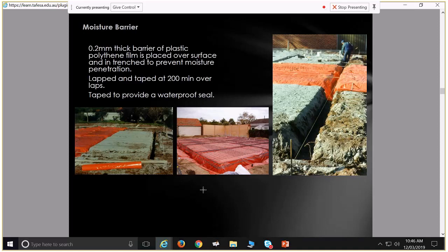But how about the termite sheet? Will it be below this sheet? Oh, termite? No, so that termite cordon barrier that I passed around, you can use instead of this. No, if we are going for this sheet, yes, there we will be putting that termite sheet.